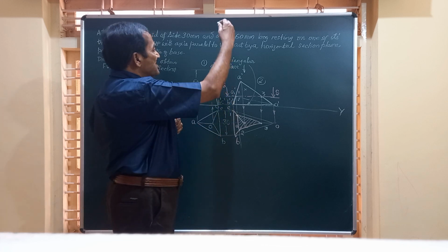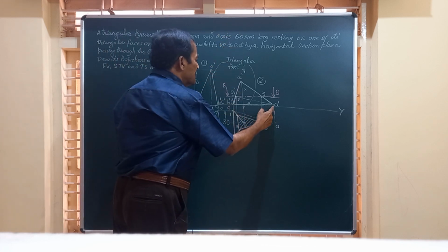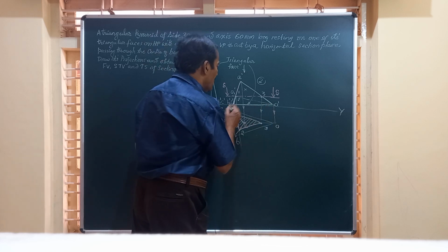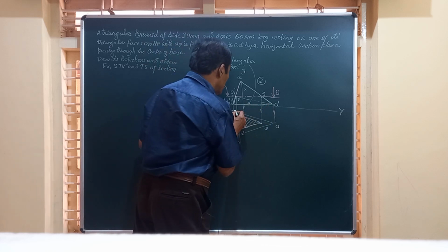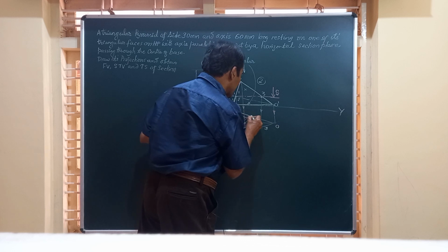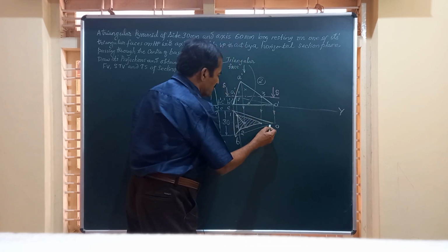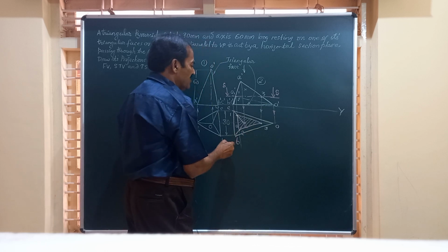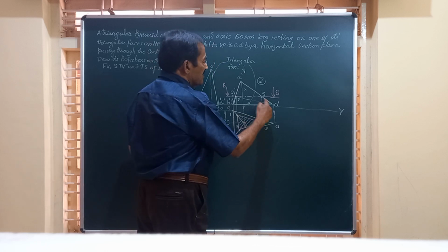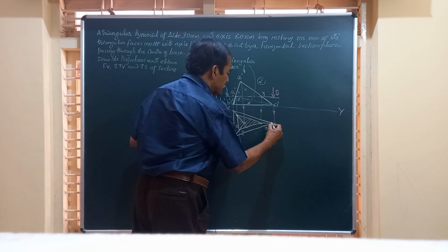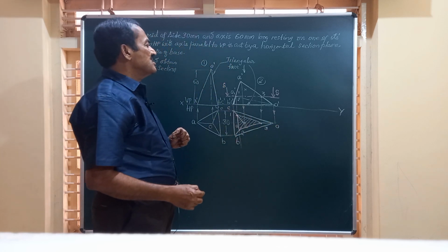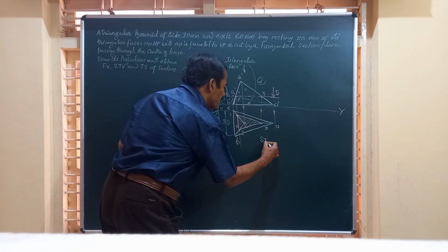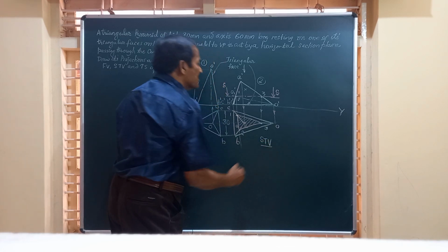Friends, if we observe the top view, the slant edges O dash B dash and O dash C dash are retained. So I am going to draw the corresponding lines here. O to C, O to B, these are retained. And friends, here this portion O to C is also retained. So friends, this is how we obtain the sectional top view of the solid, that is STV.